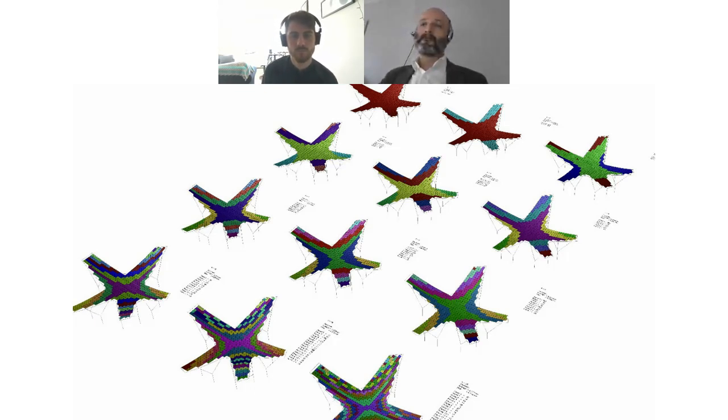So we developed a script that could analyze the panels and, based on their geometry, group them into sets of similar panels. Therefore, all of the panels in each group could then be replaced by the average panel, minimizing the number of unique panels and also the gap between them. The script used a k-means clustering algorithm, a type of unsupervised learning algorithm, which is used for a variety of applications, from analyzing consumer markets to even astronomy. So we ran the script, increasing the number of groups from 2 up to 36, analyzing the resulting deviations, both the maximum deviation and the average, also the number of panels in each group and a few other characteristics.